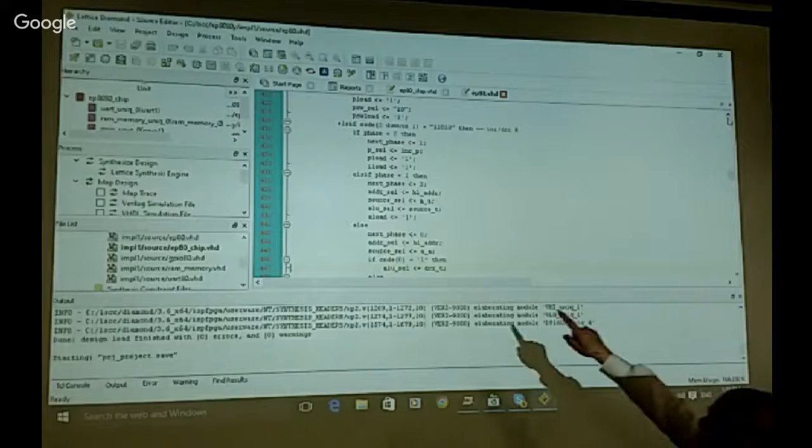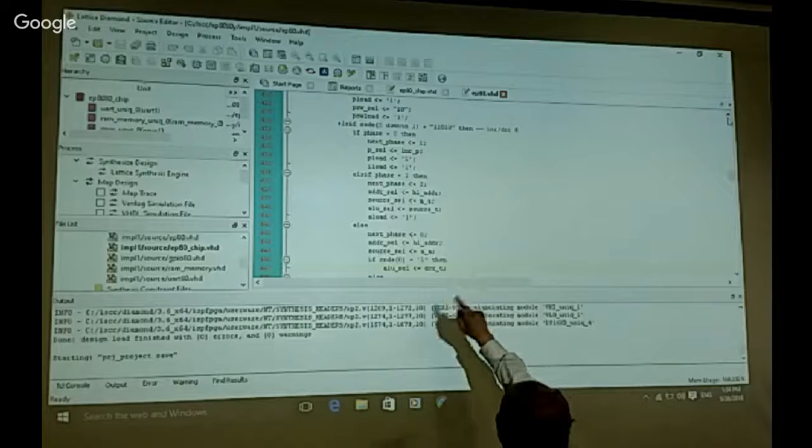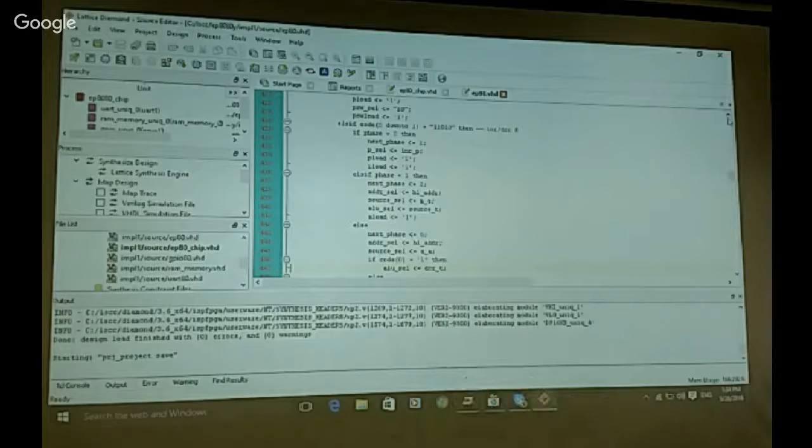Okay. So this instruction is to select the proper multiplexer in front of the proper register, and then give the proper load signal, so that on the rising edge of the next clock, the data selected by the multiplexer gets loaded into the proper register, and that's all instructions are doing.